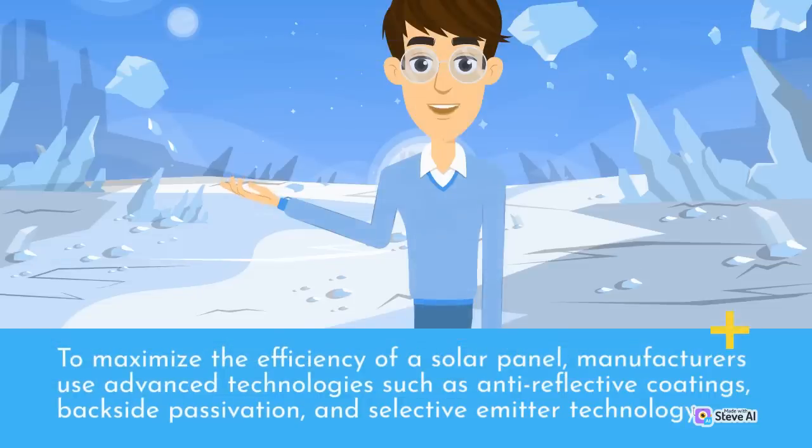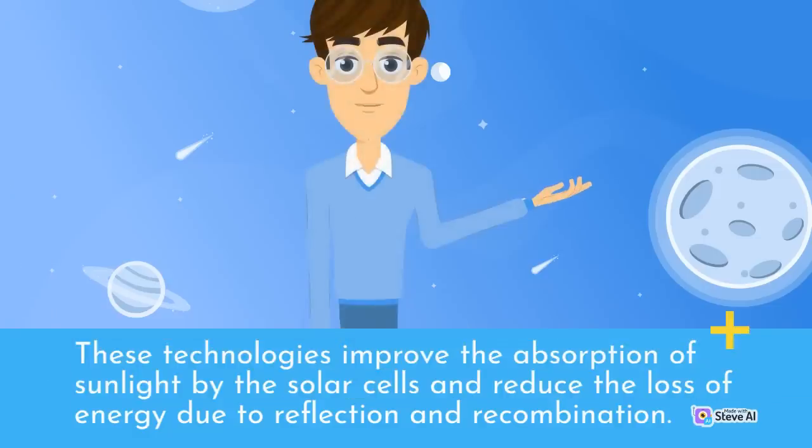To maximize efficiency, manufacturers use advanced technologies such as anti-reflective coatings, backside passivation, and selective emitter technology. These technologies improve the absorption of sunlight by the solar cells and reduce the loss of energy due to reflection and recombination.